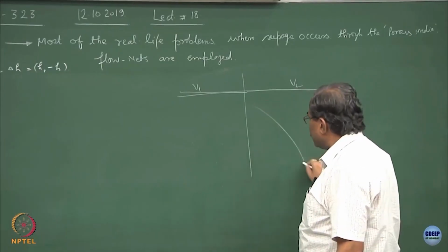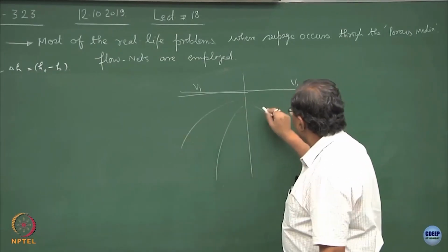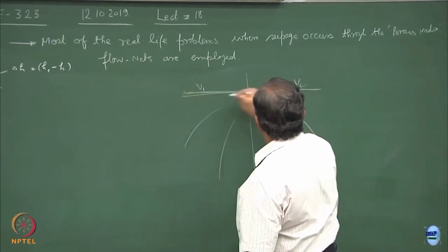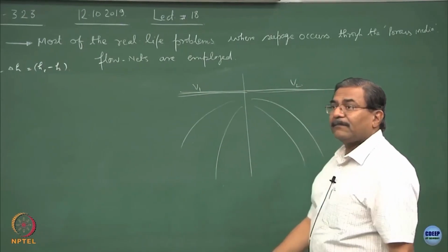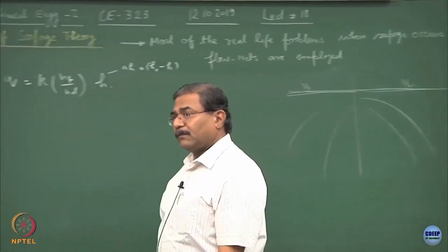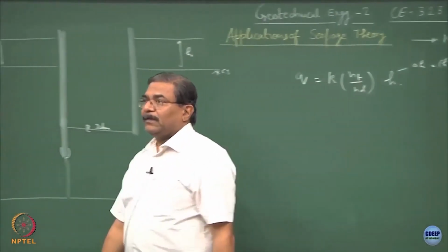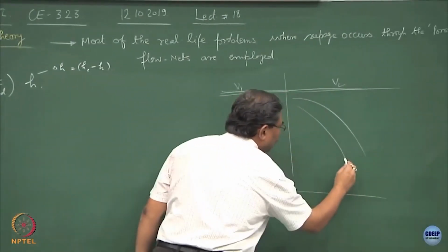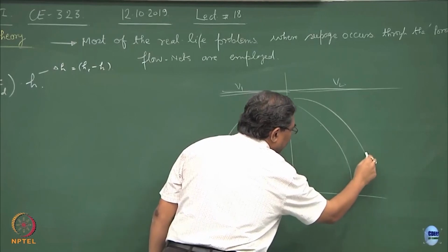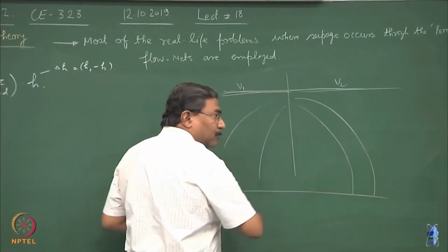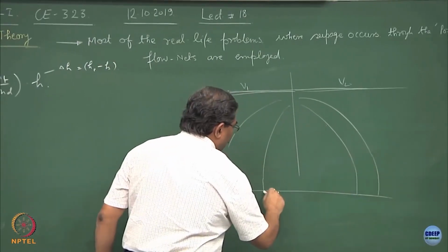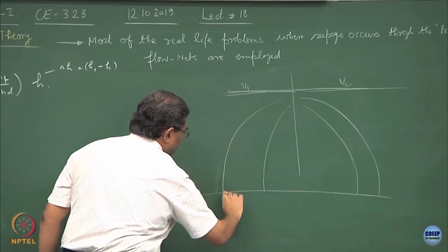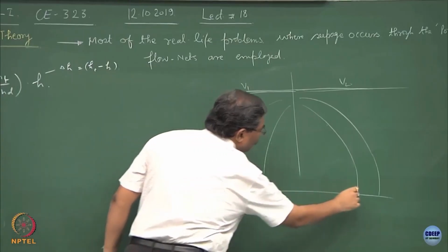So, this becomes an equipotential line, fine, and one of the lines is this, another line is this, alright, done. And at the bottom portion, if it is impervious, all these equipotential lines will come and hit the flow line, because the bottom is also a flow line, as we discussed. So, they will be perpendicular, 90, 90 and so on.